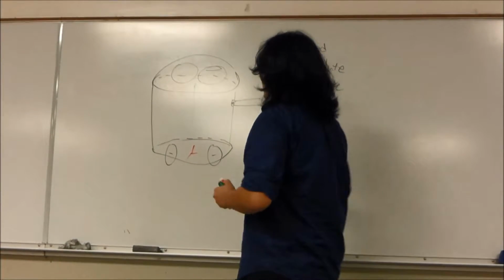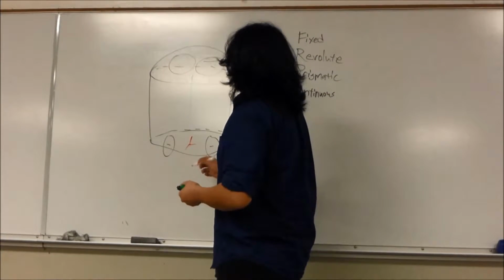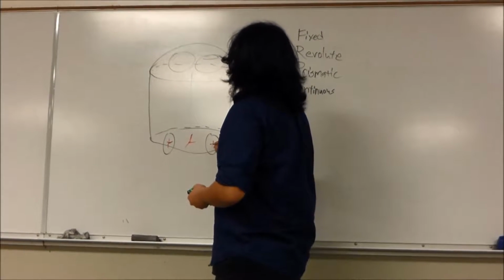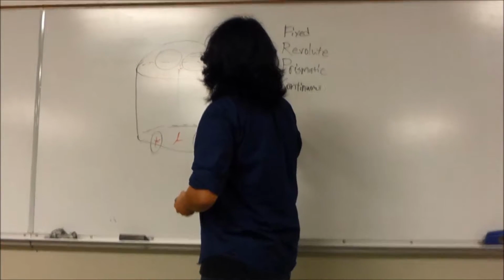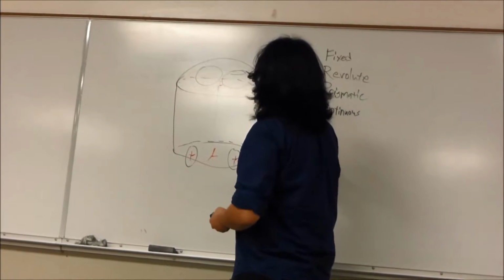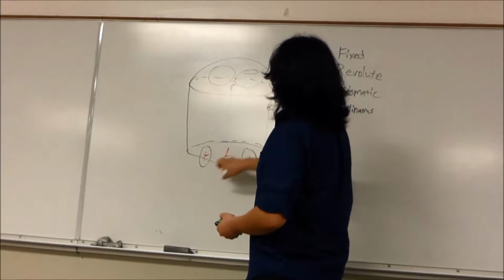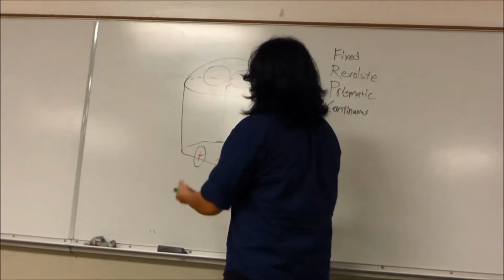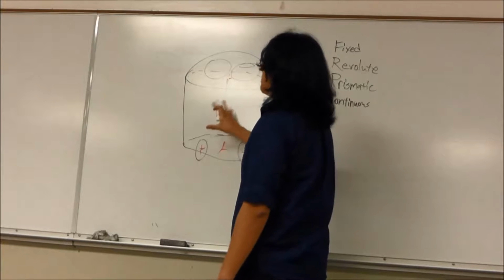RAS, I won't get into RAS yet. That's our base frame. Other frames on him are, for example, the frame of where his wheels are, the frame of how his head is rotated, the frame of this body here. And these frames can change based on what the location of your joints are. There are other frames not a part of R2-D2 that he might have to conceptualize, such as world frames, things that aren't attached to him.